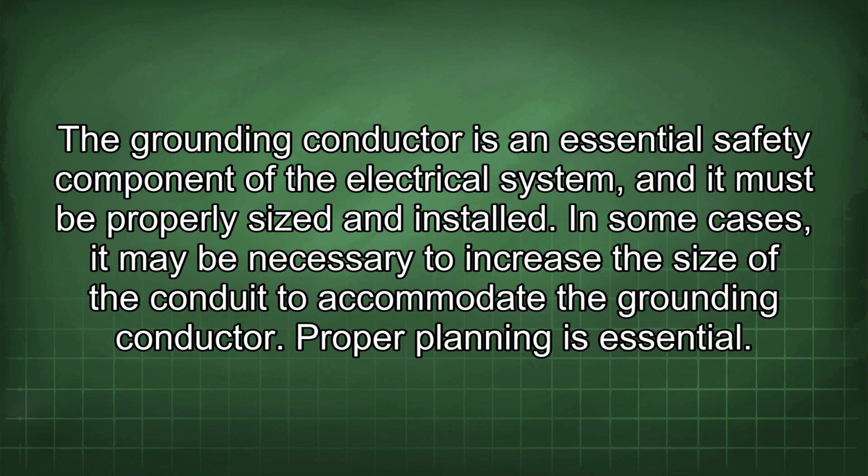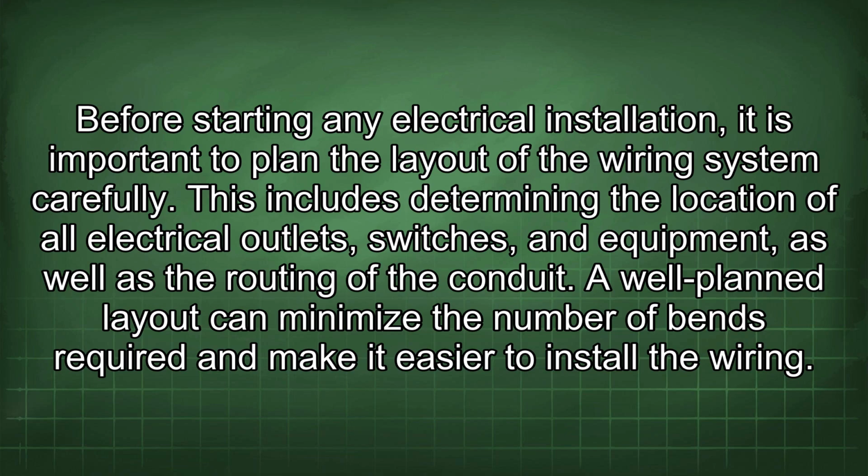Proper planning is essential. Before starting any electrical installation, it is important to plan the layout of the wiring system carefully. This includes determining the location of all electrical outlets, switches, and equipment, as well as the routing of the conduit. A well-planned layout can minimize the number of bends required and make it easier to install the wiring.